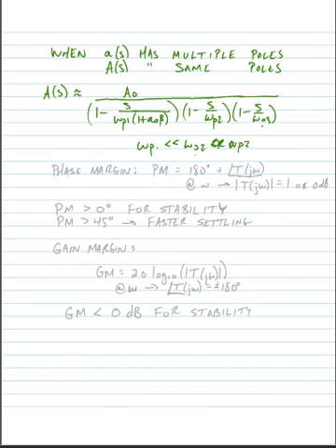We began looking at this in class the other day, but we can define a specification that will tell us something about stability called phase margin. And phase margin is defined as the difference between 180 degrees and the angle of our loop gain at omega when the magnitude of the loop gain is equal to 1, or in dB, 0 dB.